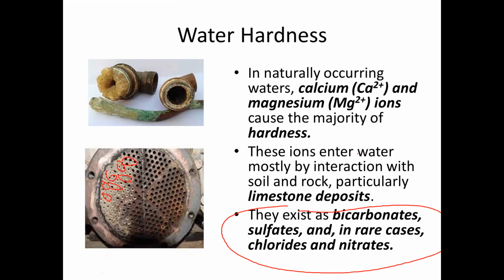Now, it solidifies and precipitates, and at higher temperature, instead of dissolving in the water, it is taken up in our boilers. That's why this is very harmful also. Later on, you will learn how important water hardness is, because it also causes scaling. With scaling, it could potentially cause problems like explosion, no?